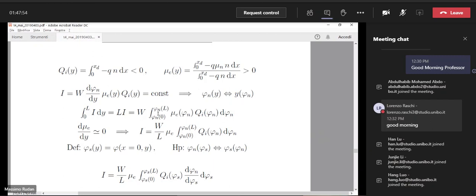And the answer is, in this condition, that is when the channel is well formed, the vertical component of the field is practically constant at each position. And the reason is that in the strong inversion condition, the surface potential is substantially equal to 2 phi f.